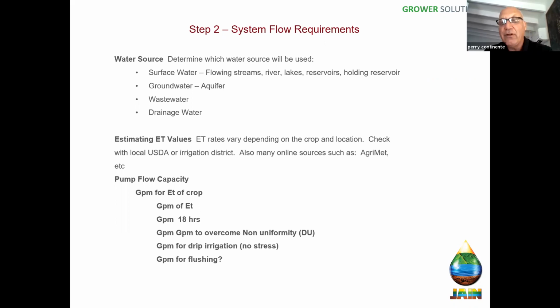We know in the Central Valley that for almonds, we're going to make sure that we provide 0.36 inches of water of application rate to the grower in order for him to be able to meet ET at full maturity in the worst possible case scenario.